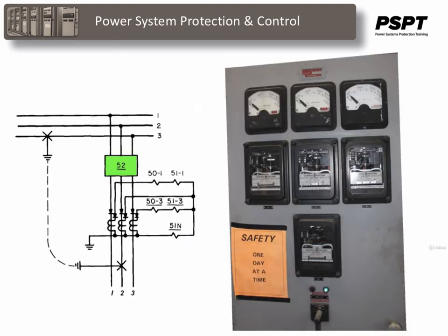A minimum of 3 overcurrent relays and a total of 3 current transformers are required to detect all possible faults in a 3-phase AC system. 2 of these relays are usually connected in the phase circuits, and the third relay is usually connected in the residual circuit of the current transformer as shown here. Sensitive ground fault protection and protection against simultaneous grounds in different parts of the system is provided by this arrangement, whether the system is grounded or ungrounded.